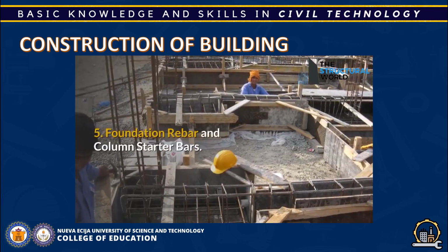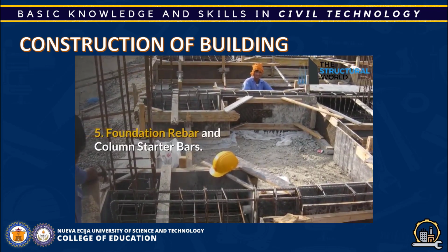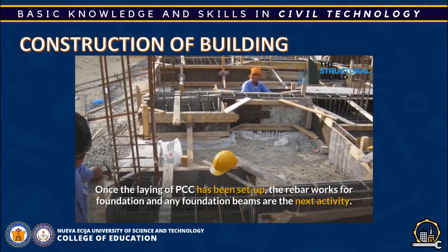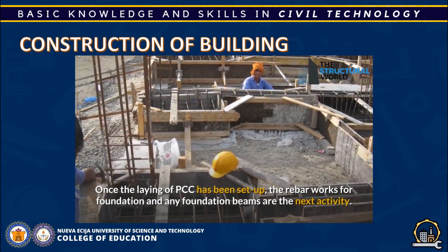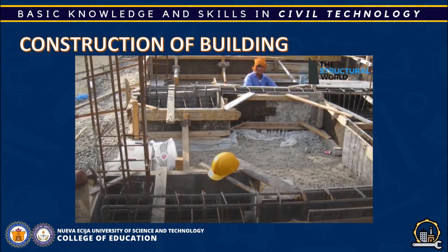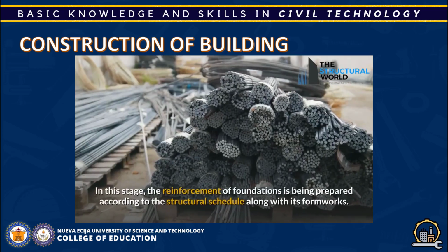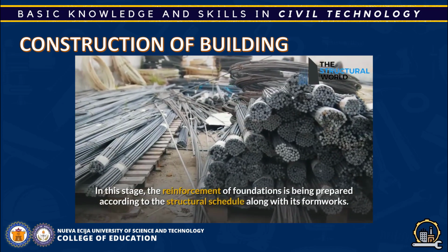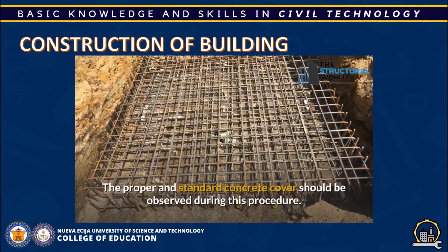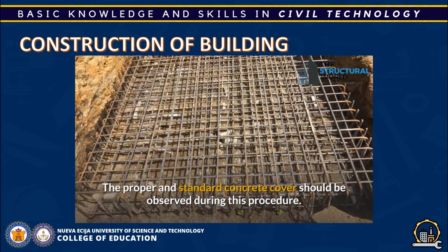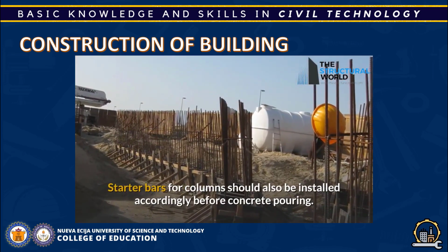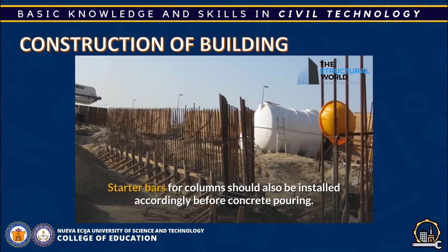5. Foundation rebar and column starter bars. Once the laying of PCC has been set up, the rebar works for foundation and any foundation beams are the next activity. In this stage, the reinforcement of foundations is being prepared according to the structural schedule along with its formworks. The proper and standard concrete cover should be observed during this procedure. Starter bars for columns should also be installed accordingly before concrete pouring.